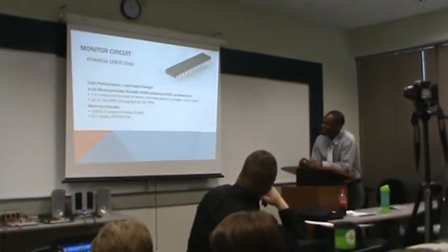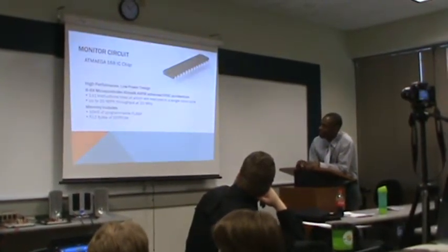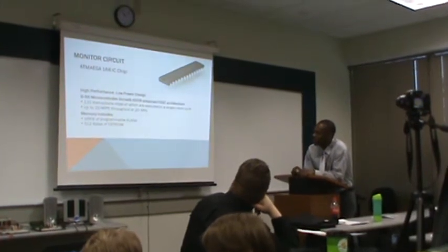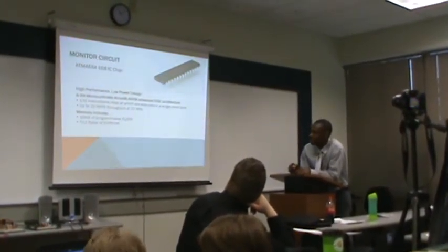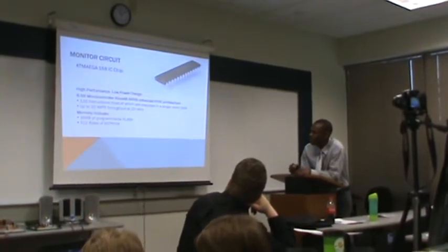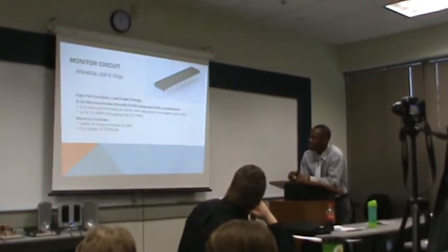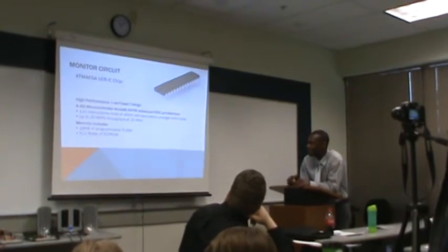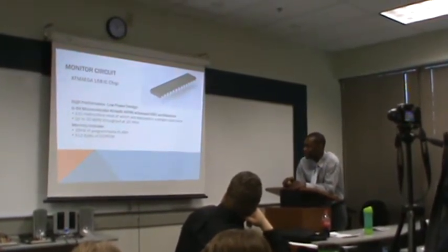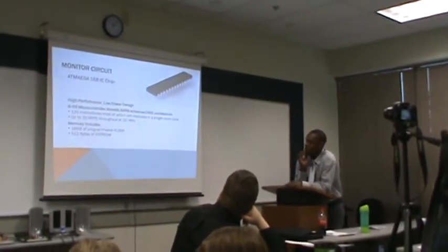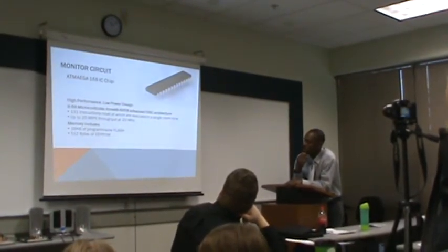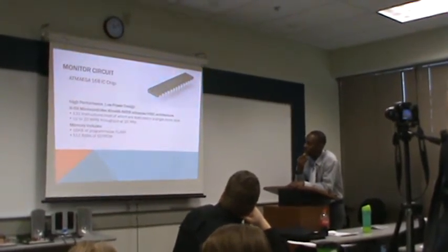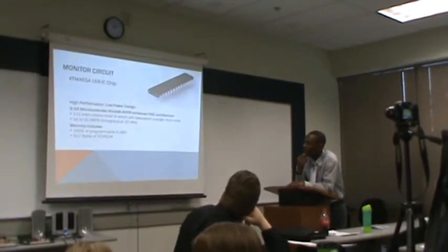ATmega168 IC chip. High performance, low power design, 8-bit microcontroller. 131 instructions, most of which are executed in a single clock cycle. Up to 20 MIPS throughput at 20 megahertz. Memory includes 16 kilobytes of programmable flash and 512 bytes of EEPROM.